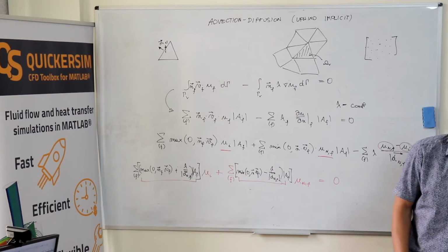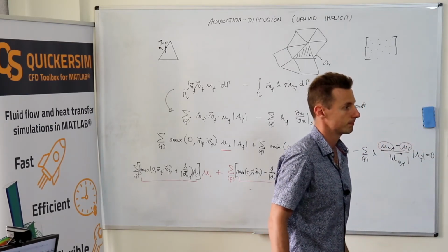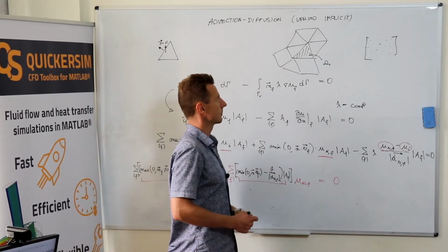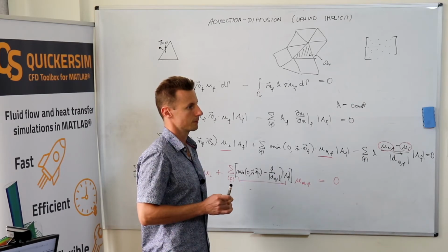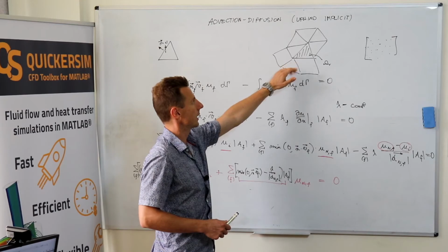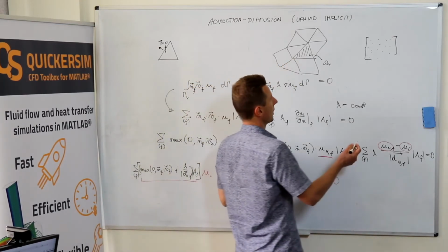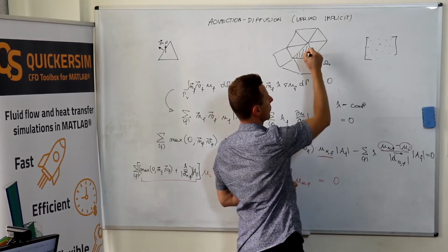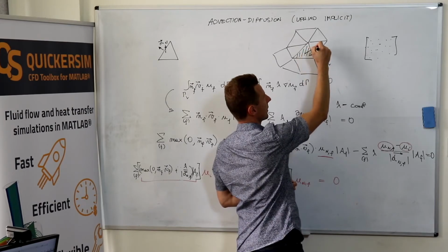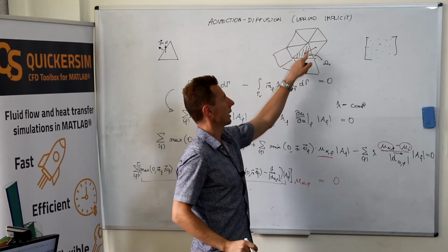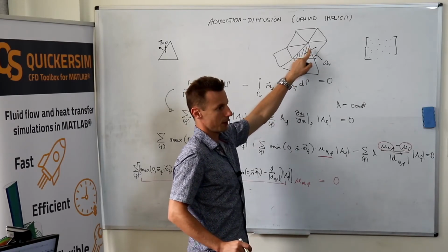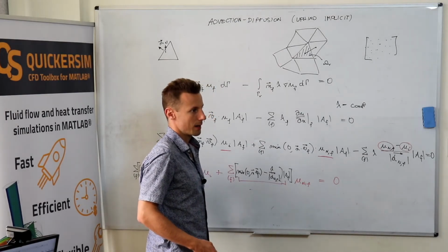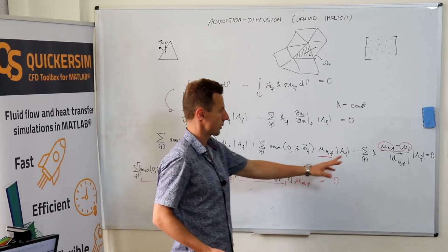Questions? Is there any motivation to use a certain type of elements in finite volume? Like here, for example, we have a mixture of quads and triangles, and apart from the geometry of the problem, only for numerical reasons. Well, actually, probably only the things that I have discussed when talking about meshes. Generally, if you use quads, or even triangles, you would like to generate the mesh in a way that the line segments connecting the neighboring centroids are at a 90 degree angle with respect to the edge, because then you have little mesh skewness and relatively small error of the discretization of, for example, the diffusive flux.